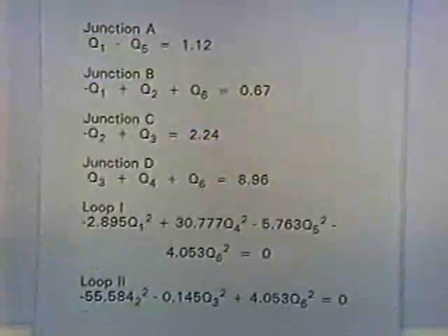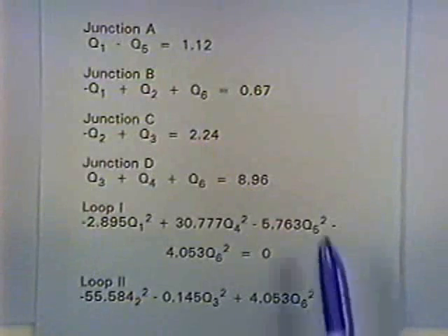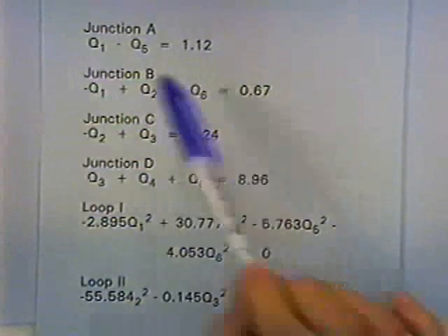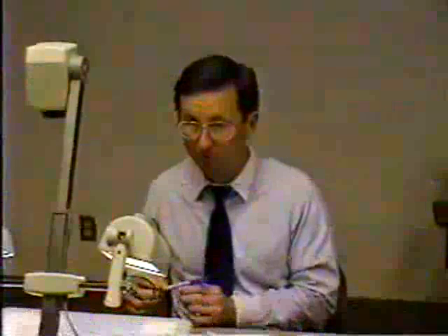Now the reason that there are different computer codes and different approaches for solving pipe network analysis problems is that they solve the system of equations differently. And we're going to use the old classic method, called the Hardy-Cross method. Before we go into the Hardy-Cross method, the point here is, once you've got the equations, any system for solving a set of nonlinear equations would solve the problem.